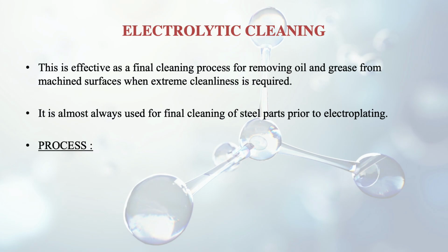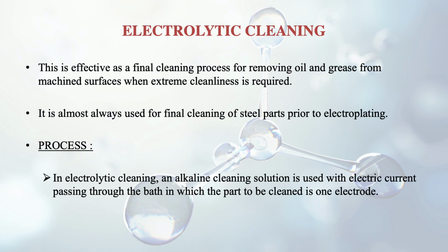The process for this electrolytic cleaning is that an alkaline cleaning solution is used with electric current passing through the bath, in which the part to be cleaned is one electrode. So the part that has to be cleaned is made as one electrode in case of this type of cleaning.